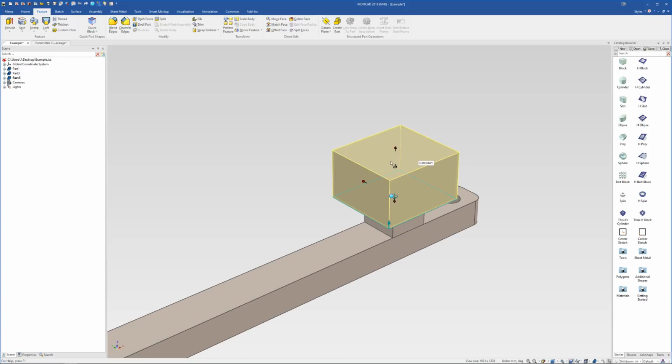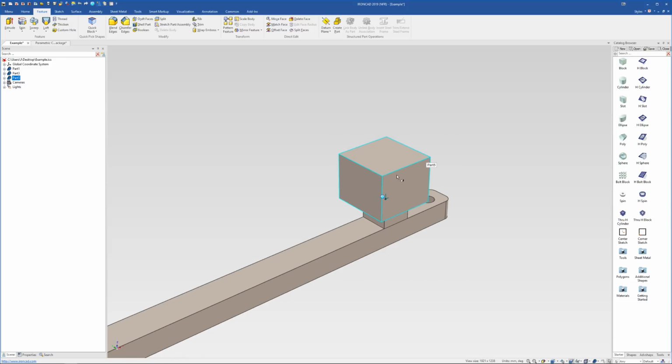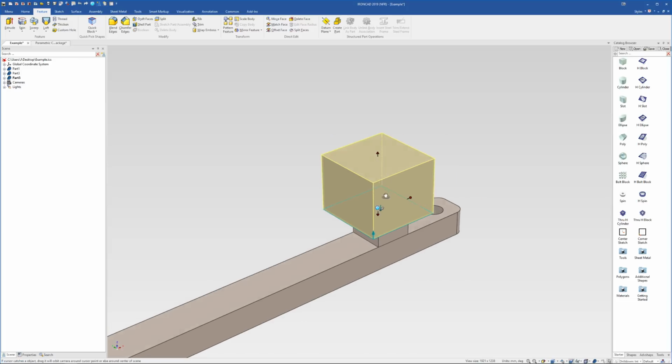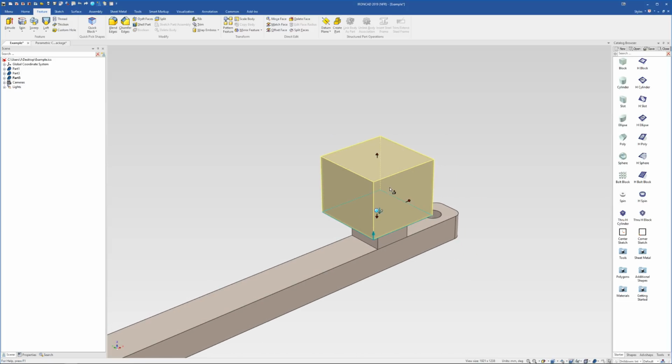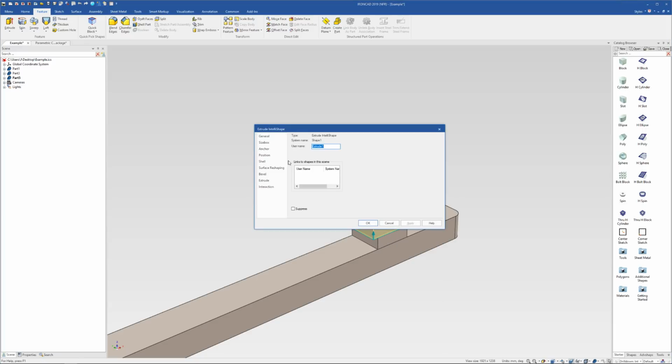But now if you go down to click onto the IntelliShape level, you can only adjust with these handles. You don't have the side handles or anything like that. You've got the cross-section handles, which can sometimes be useful, but they aren't as useful as the side handles. So what you can actually do is activate the side handles here. You can right click, go into the IntelliShape properties, and you've actually got the size box handles sitting in here. So what you have to do is turn them on.